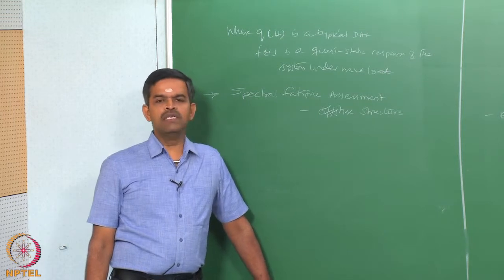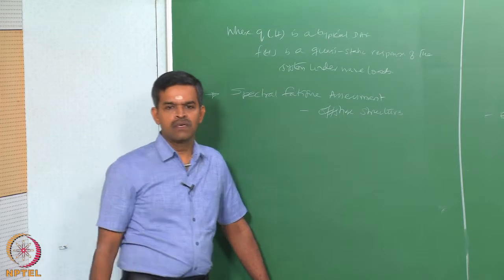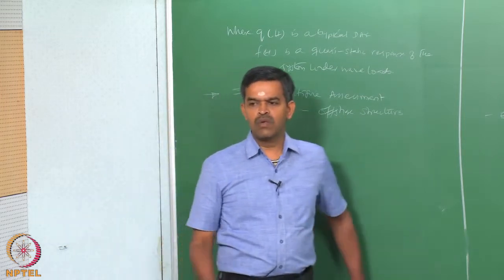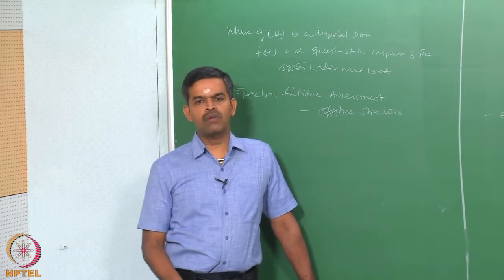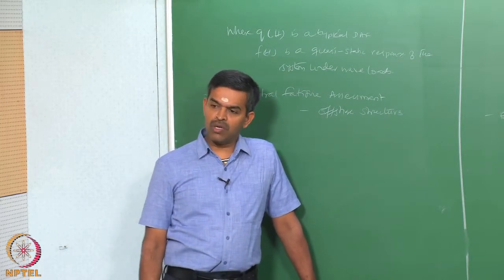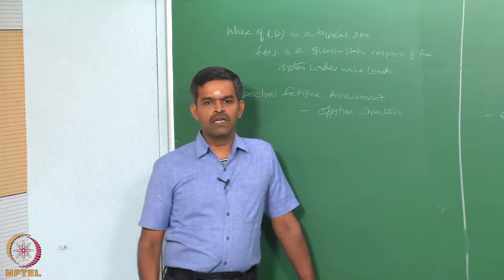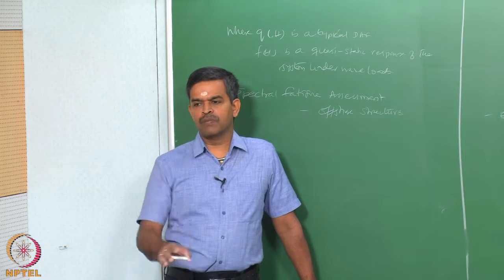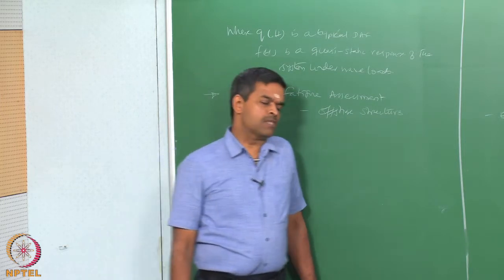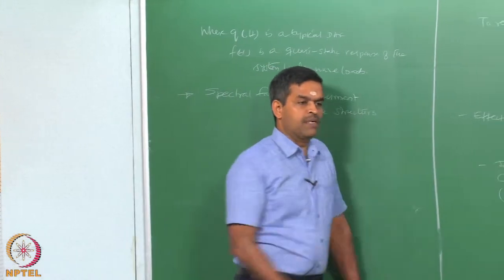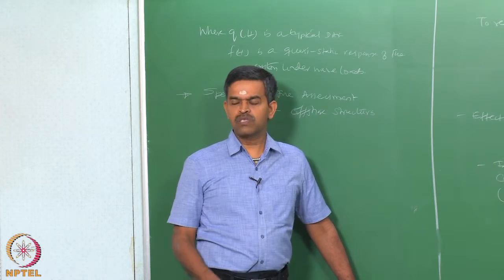Although the Gaussian sea surface forms the basis for spectral analysis, the load acting on the system and the response, which is the effect of the load on the system, can become also non-Gaussian unless a consistent linearization procedure is adopted in the through and through analysis. So, we are not bothered about the response of the system for the fatigue assessment, but we are focused on the stress response of the offshore system.